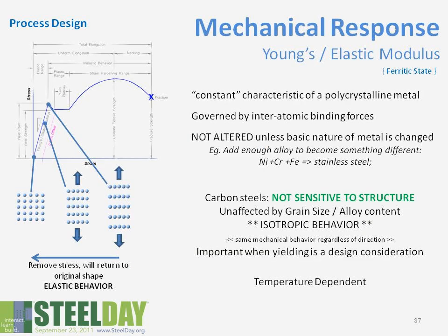So practically, what do these strengthening mechanisms do? How does that give us mechanical response? If you're familiar with the stress-strain diagram, you'll know initially as we load a steel, we have an elastic response. What essentially happens is we take a lattice at rest, we stress it. When we remove the stress, it behaves 100% elastically, goes back to the original shape.